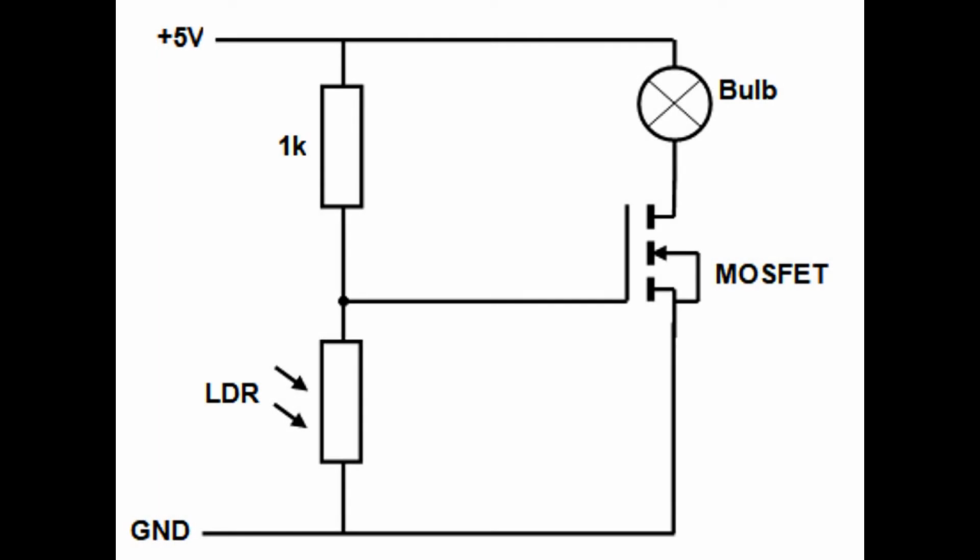Here I have an LDR potential divider driving the gate of a MOSFET which turns the lamp on when it gets dark. For our above analysis, we know as the light level falls, the LDR becomes more resistive, causing a voltage rise at the gate of the MOSFET, which will still start to turn it on. This circuit is incredibly poor without a Schmitt trigger, as the MOSFET partially conducts at low light levels, causing excess heating due to it being driven in the triode region. It fully conducts when completely dark and enters the saturation region of its response.